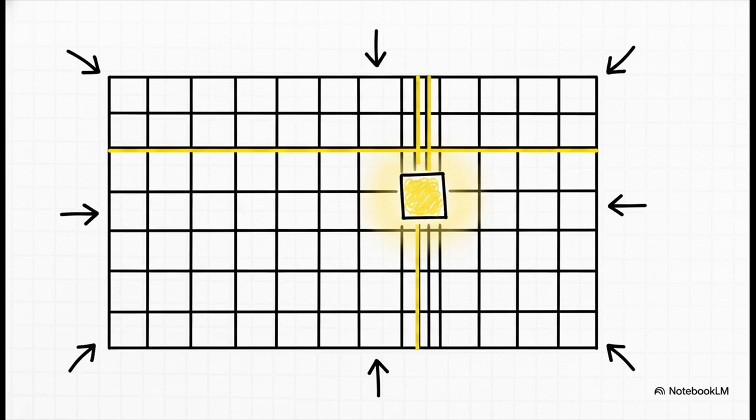Now, the absolutely crucial point here is communication. Memory cells in the exact same row connect via a common word line. Meanwhile, all the cells in a single column connect to a sense and write circuit via 2 bit lines. It's this brilliant architecture that seamlessly handles all the data input and output across the entire chip.